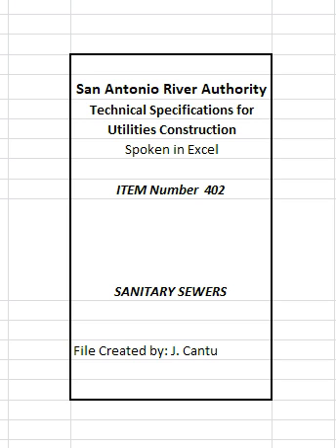A. Interceptors shall be constructed in accordance with the design approved by the San Antonio River Authority, consisting of a minimum of 2 compartments with fittings designed for grease retention and provide for a minimum of 30 minutes retention. B. There shall be an adequate number of manholes to provide access for cleaning all areas of an interceptor, 1 manhole per trap compartment. Manhole covers shall be gas-tight in construction, having a minimum opening dimension of 20 inches, 0.5 m. C. In areas where traffic may exist, the interceptor shall be designed to have adequate reinforcement and cover.